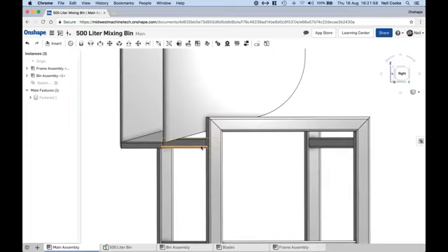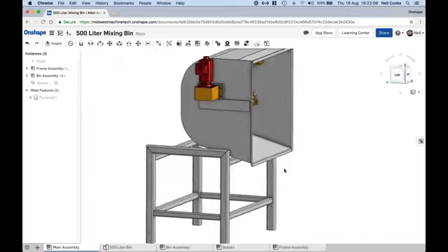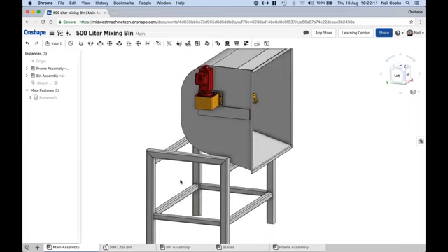Okay, so I've now set up the design problem, or the solution, I should say. Now I just need to work out the linkages that make up this design. All right, now the way we can do this in Onshape is to use the in-context editing. Now, in-context editing allows you to position members of an assembly or components from an assembly in multiple locations and display them in the Part Studio.